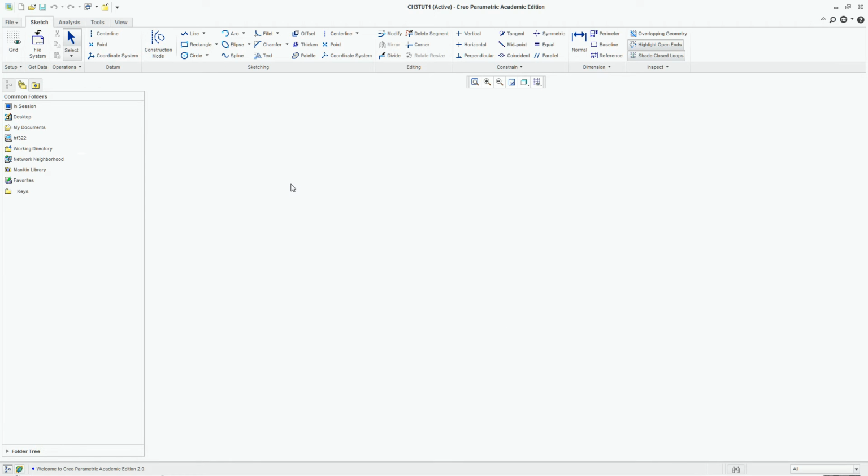And the way that I'm going to do this one, in the past I've always gone and done either 2 lines or drawn a first circle. So I'm going to continue that same process and just draw my first circle. Once I have my first circle drawn, I can dimension this. Now, it has a radius of 90, so I need to make its diameter 180.